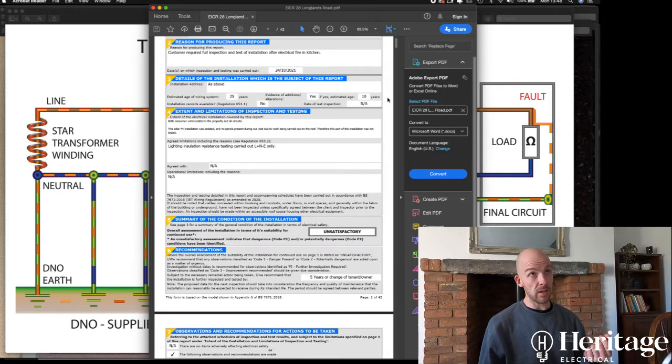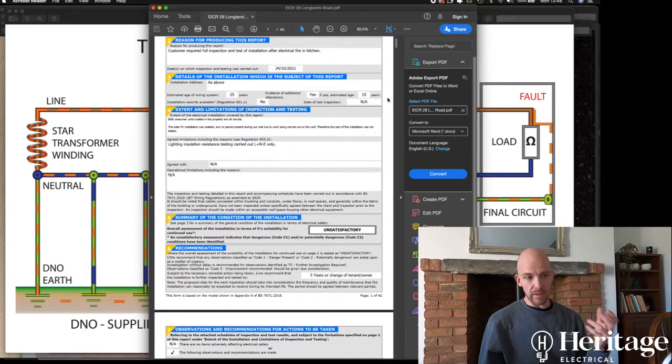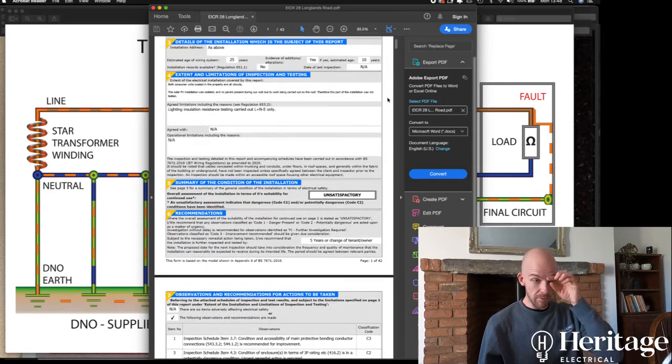That's because there were some non-fire rated downlights with some very hot running halogen lamps in there, and the customer had put in insulation without any sort of fire hood or replacing the fittings for fire rated fittings, and so that almost caused an electrical fire. Burned some of the cabling, so we recommended a condition report after that, and this is where we are.